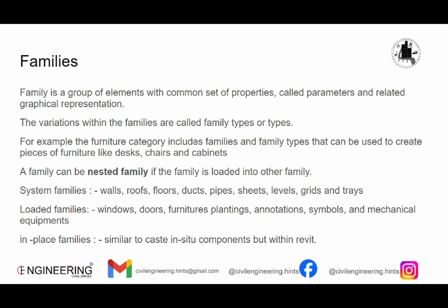What are system families? The types of families are system families, loaded families, and in-place families. System families are presets from Revit architecture and are essential for any modeling discipline, like walls, roofs, floors, ducts, pipes, sheets, levels, grids, and electrical trays.